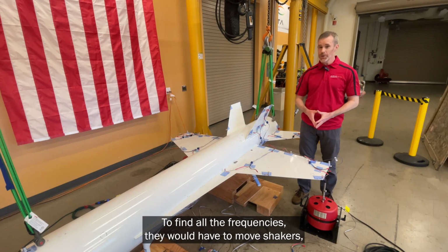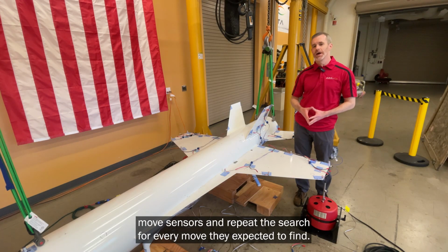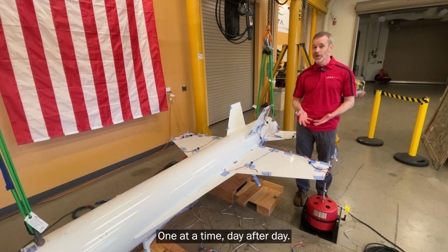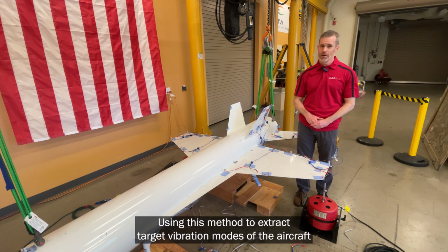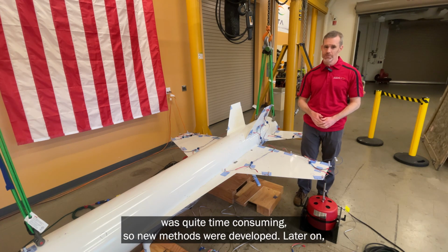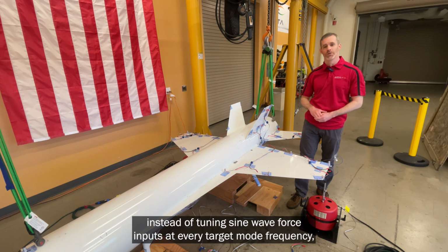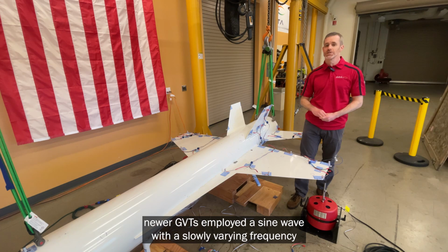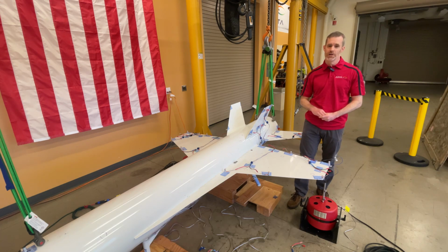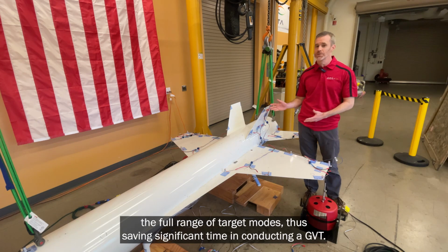To find all the frequencies, they would have to move shakers, move sensors, and repeat the search for every mode they expected to find, one at a time, day after day. Using this method to extract target vibration modes of the aircraft was quite time-consuming, so new methods were developed. Later on, instead of tuning sine wave force inputs at every target mode frequency, newer GVTs employed a sine wave with a slowly varying frequency, starting low and sweeping up. The full sweep would envelope the full range of target modes, thus saving significant time in conducting a GVT.